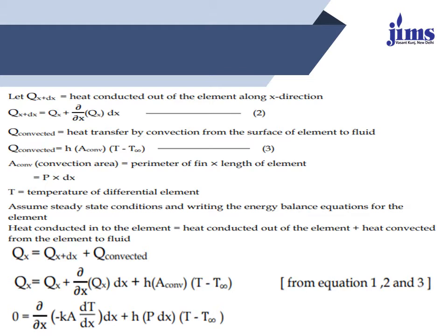As per this equation, the heat conducted into the element should be equal to the heat conducted out of the element plus the heat convected from the element. So this is a basic fundamental heat transfer equation. Mathematically, Qx is equal to Qx plus dx plus Q convected, or Qx is equal to Qx plus del over del x multiplied by dx, plus h multiplied by area of convection multiplied by T minus T infinity.